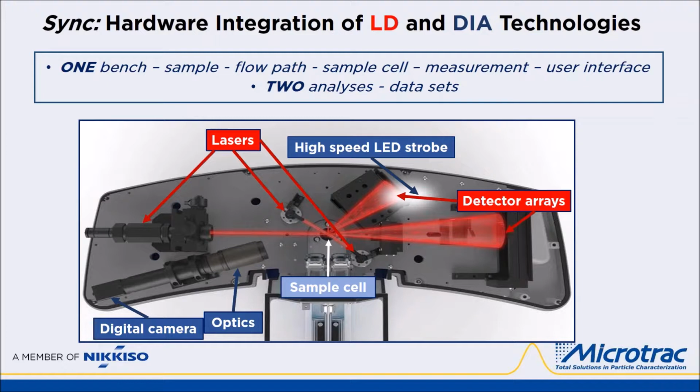Clockwise from the top, the laser diffraction hardware includes the 3 lasers with an option of red at a longer wavelength or blue, a shorter wavelength, for 2 of the lasers for highest accuracies at different ranges, and 2 diode detector arrays on the right measuring scattered light from 0 to 165 degrees.